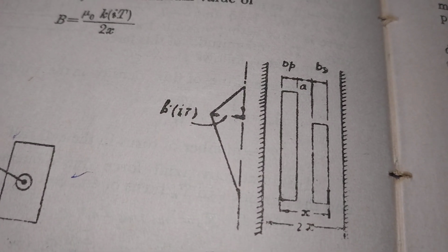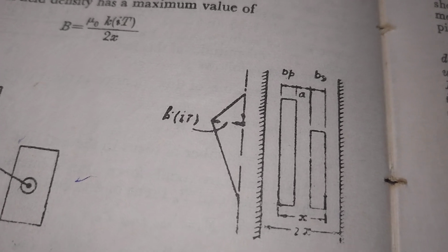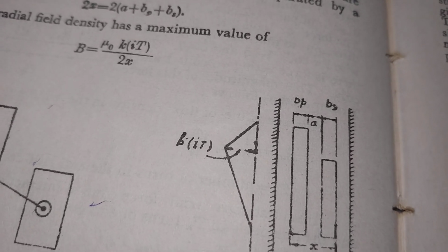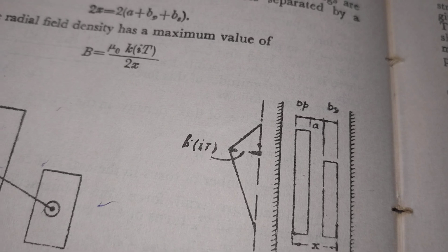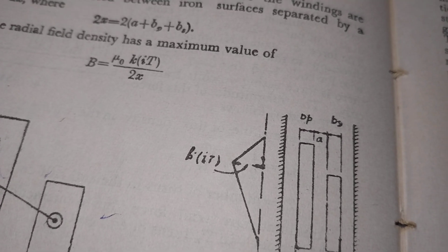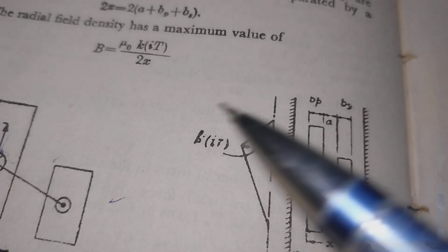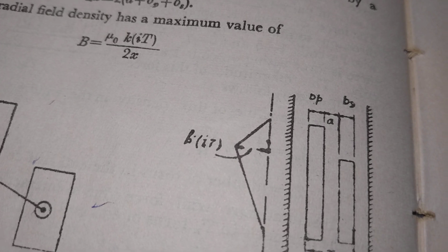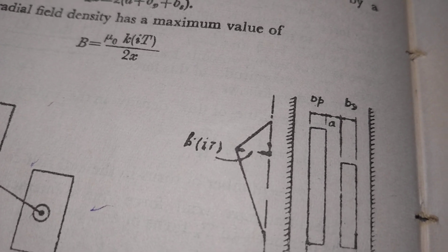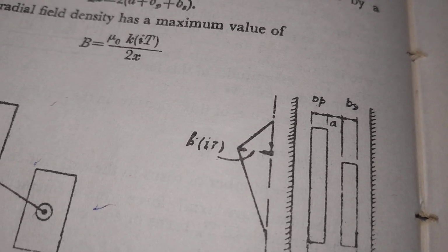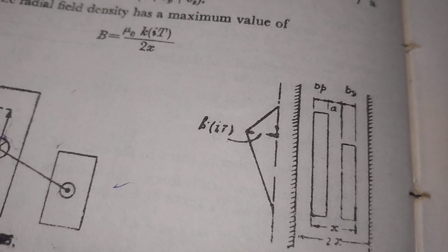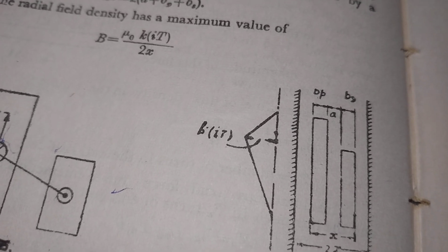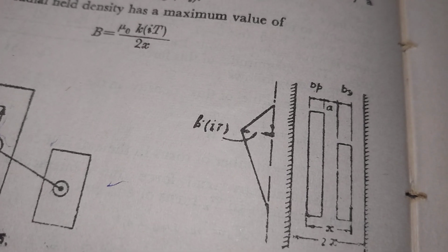Inward axial forces are taken by the windings themselves. Inward radial forces are passed on to the formers, packing pieces and cores. Outward axial forces must be withstood by the end insulation. A well-constructed transformer should have suitable choice of conductor dimensions and inter-turn insulation, and the coils well supported and braced with compressive stress kept in view.